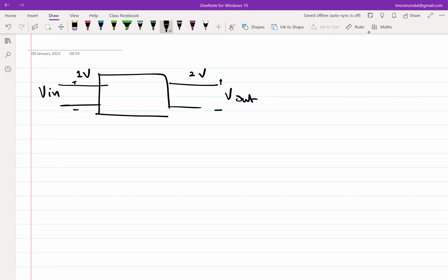Now, this is just an example that I took. It's quite possible that I have a system where I give an input at one frequency and it comes back at a different frequency. And if the final difference frequency, let's say, is DC, then it's quite possible that I take some frequency components, up convert them to some other frequency component, down convert to DC, and whatever is the resultant is something which is more than the input. Possible, right?